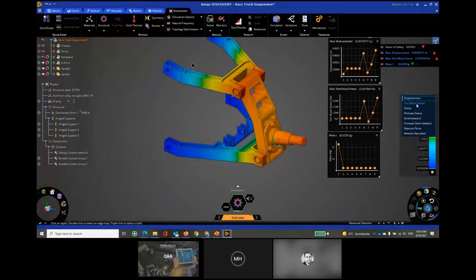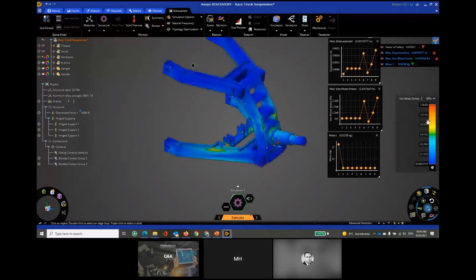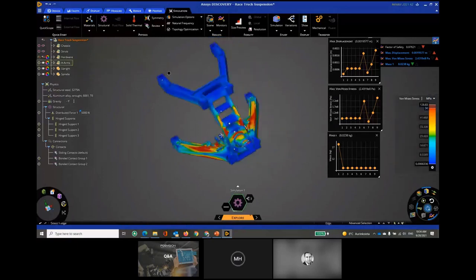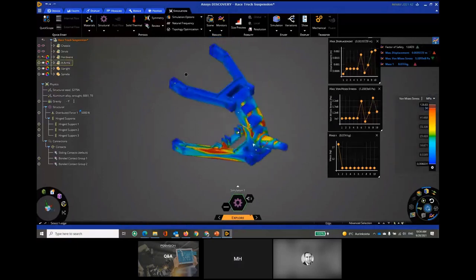If I want to go for stresses, for some reason, let's go for megapascals, and let's limit ourselves to, let's say, 50, just to get some kind of a result from the stress pattern. You will see that we have something in here. Then, for example, joints: we have this kind of sliding contact in here.